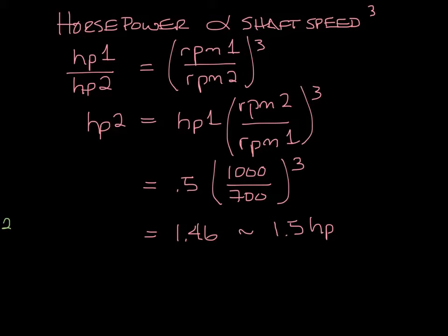So this is something to think about in HVAC systems. If you have more pressure than expected, you have to speed up the fan to get the airflow you need. The energy you'll use goes up as the cube of the RPM. Now with fractional horsepower motors, like those used in fan-powered boxes, this may not be a big deal. But the fan laws apply to all the fans in your HVAC system, and that could add up to a lot of extra energy usage.